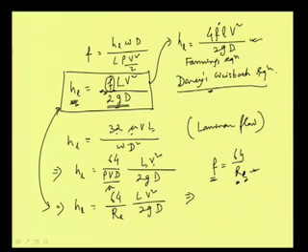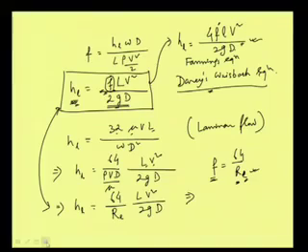Suppose we get the friction factor value for one expression and then apply it to the other, then the head loss that we get will be on the lower side, it will be underestimated. So, we should know for which formula this friction factor value is being given, and use that friction factor appropriately.